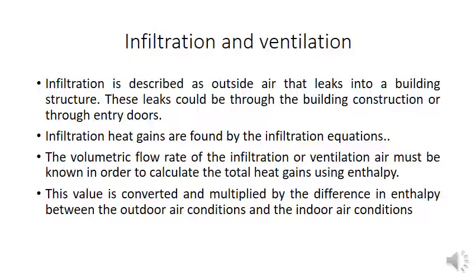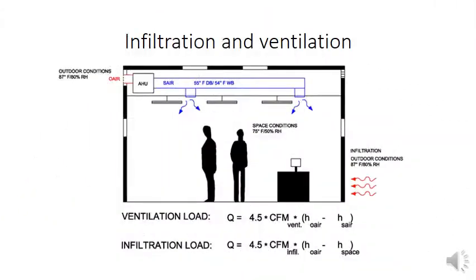The volumetric flow rate of the infiltration or ventilation must be known in order to calculate the total heat gain using the simple enthalpy expression. This value is converted and multiplied by the differential enthalpy, which is based on the indoor and outdoor air conditions.